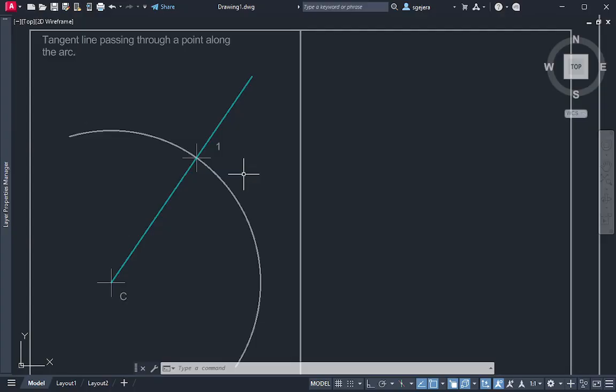Okay? So again, for now, I won't allow the use of object snapping for perpendicular lines. If you use object snapping for perpendicular lines, in case you have already explored, you probably noticed that it is much easier to create perpendicular lines using object snapping. But again, since we're still doing geometric construction, it's not allowed for now. Let's construct the perpendicular lines through geometric means. Okay? So, we have this.